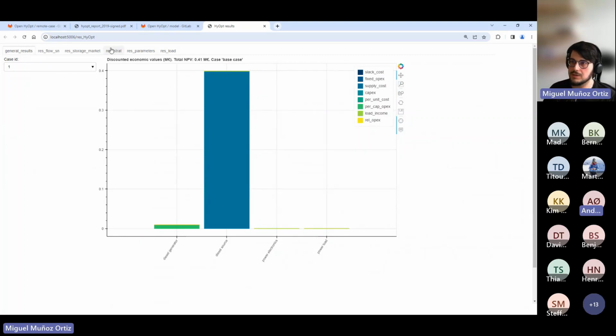This evaluates the total costs per node, so per element of your system. If you go to case number 1, you will only have your diesel source, how much diesel you pay, and here you can see the total cost of the node is 0.1399 million euros for the total 20 years. And then we have some costs associated with the diesel operation, like maintenance and replacements, and that's OPEX, operational expenditures.